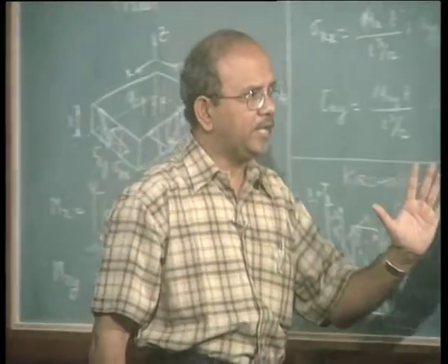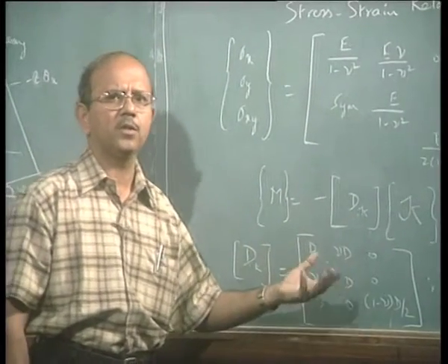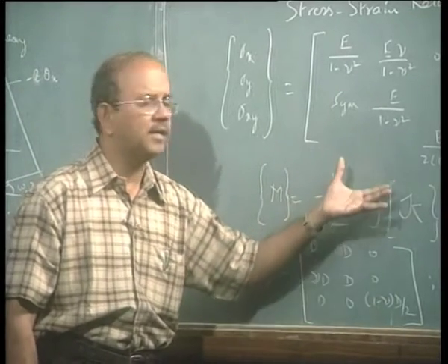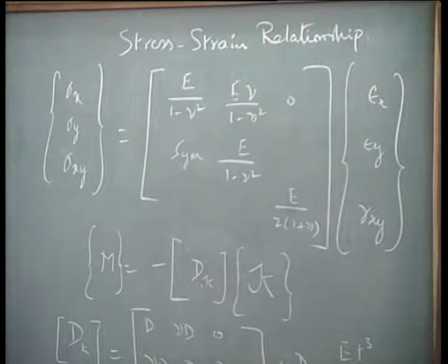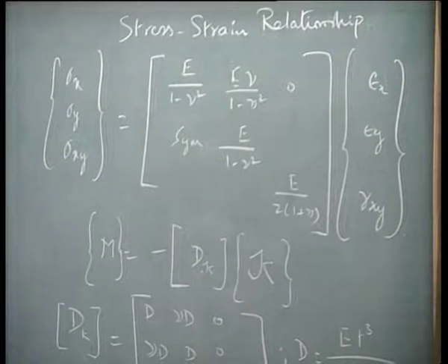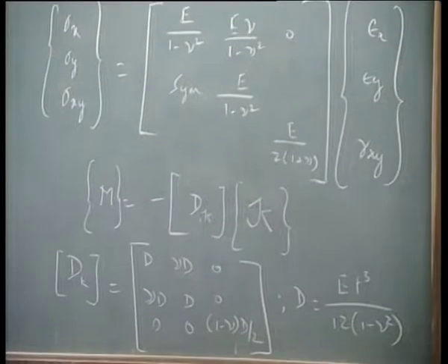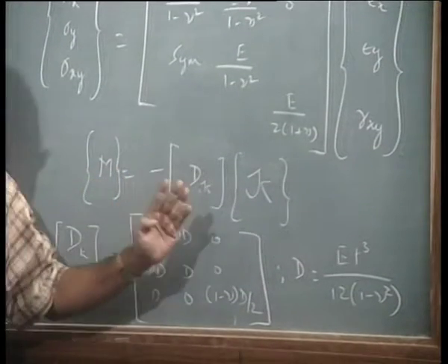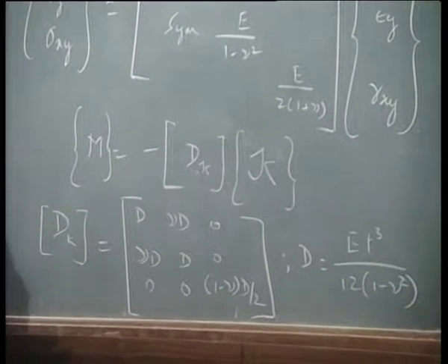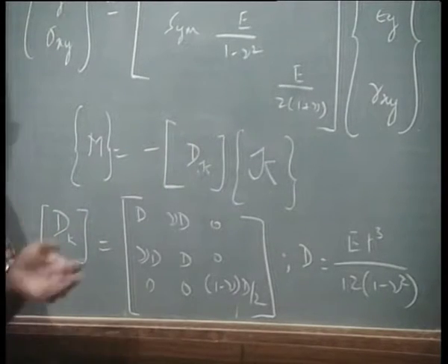So, the formulations now take off from here, and the approach is very similar. Many of the elements, older elements at least, are very similar to what we had done in our earlier classes with all other elements. In other words, we go into our variational approach. We can write down, for example, the potential energy, the strain energy using these functions, and then the formulations can proceed in a very similar fashion with interpolation functions and so on, as we have done earlier.